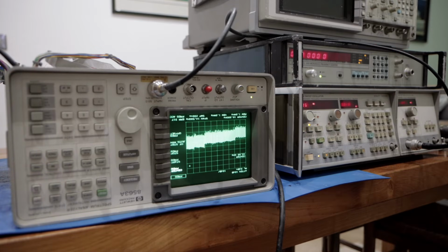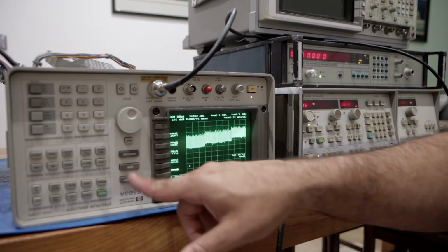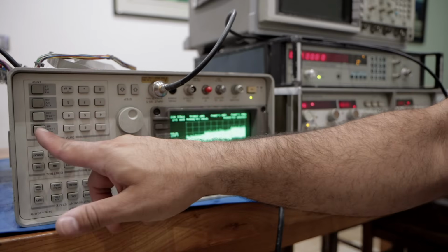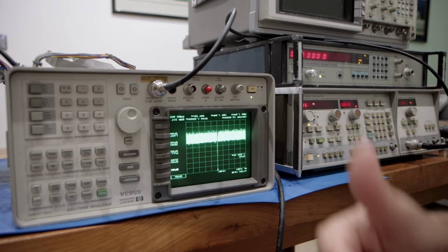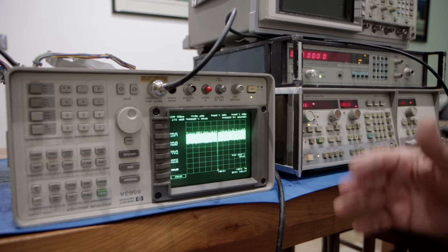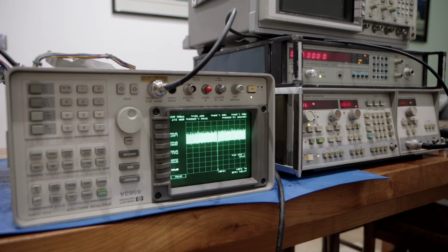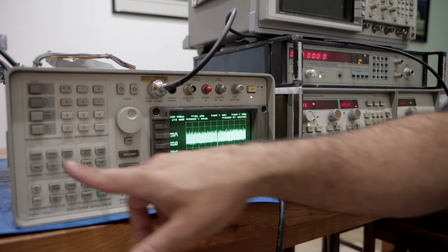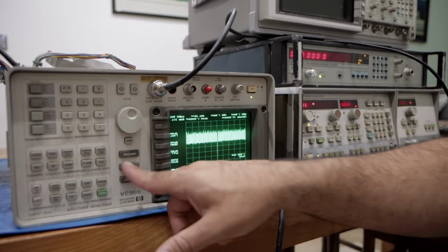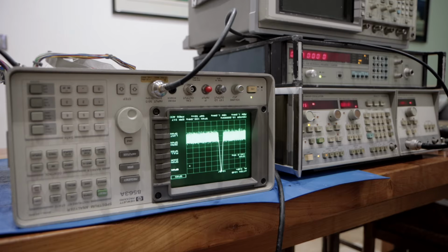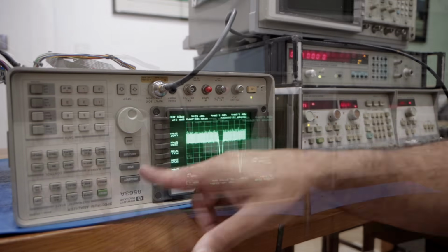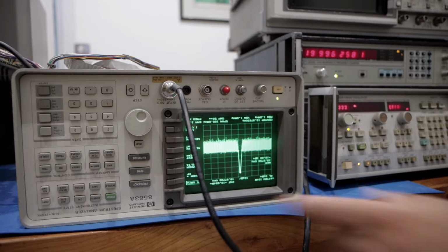Let's push it further. I'll try measuring a signal to see how the analyzer responds. I'll turn on my signal generator and apply a continuous 10 GHz signal with a 10 MHz span. Success again. This is the first time in a long while that this analyzer has actually measured something. What this means is that there are no major errors in the work I've done so far. The big oscillator is functioning correctly, and all the components I reinstalled and reconnected are working together as they should.